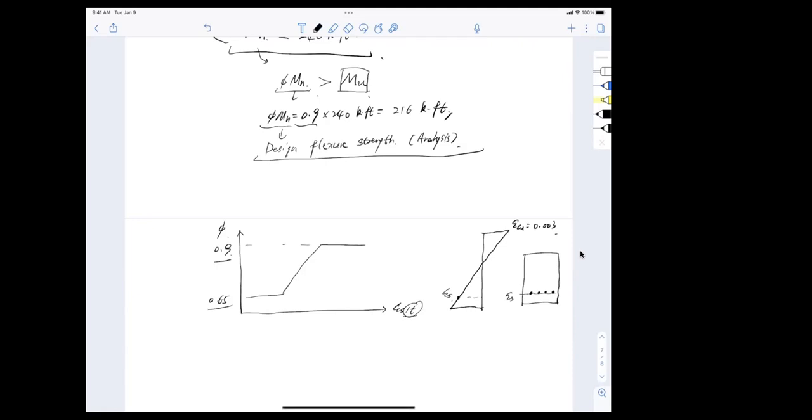All right, and now I'm going to pick on my next victim. Let's look for a D here. We're going to have two Ds. Daniel. Danny? Yeah. Hey, how are you doing? I'm good. Good. So quick question for you. Here, the strain of steel, if I have one layer, they're the same. What if I have two layers of steel? That means if I have two layers, let's call it layer 1, layer 2. In the strain diagram, my question is, which layer has a bigger strain?